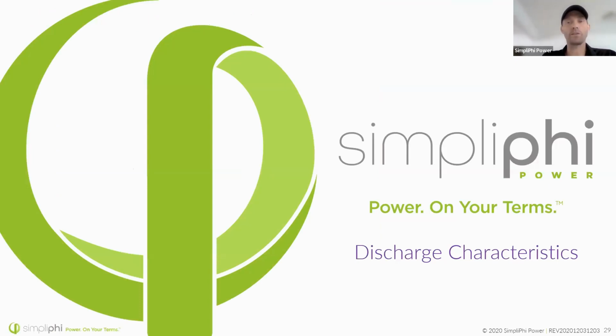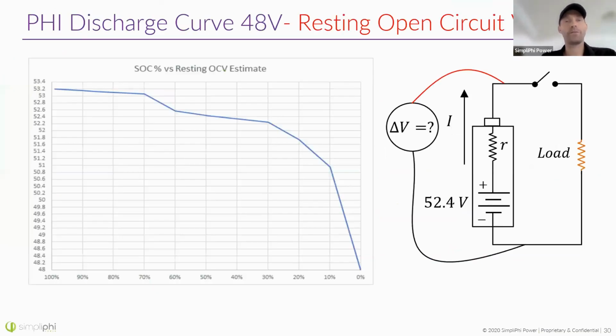What does it look like when a battery is discharging? Well, I want to show you this graph. The voltage of the battery is different depending on whether or not it's operating loads. So let's suppose you have a battery bank, and that battery bank is used to supply loads. If you're starting out with a 100% state of charge battery, you'll start out somewhere around 53 volts, a little bit above 53 volts. This depends slightly on temperature. So if you go to higher temperatures, the resting voltage would be a little bit higher for 100% state of charge. Even at really high temperatures, you won't see it exceed 54 volts. Resting voltage means the battery's voltage when it's not powering a load.